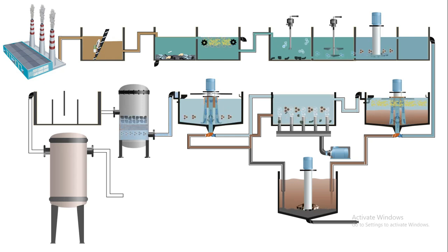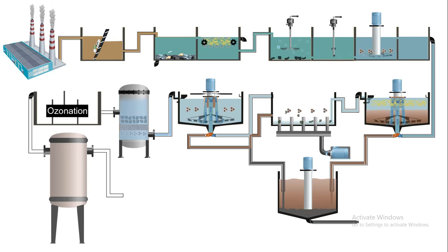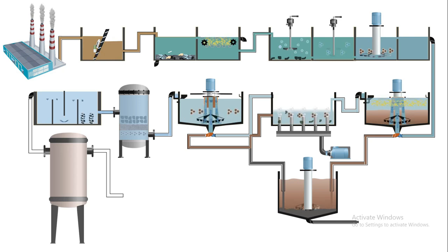After that, the clarified effluent undergoes ozonation or chlorination for disinfection. Powerful oxidizing agents like ozone or chlorine are introduced to destroy pathogenic microorganisms such as bacteria, viruses, and other microbes. This process ensures the treated water is microbiologically safe before its final use or discharge.